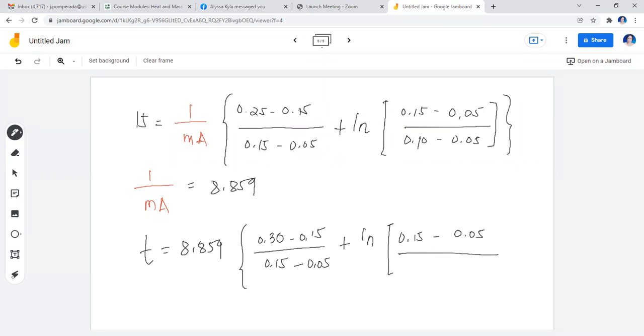In here, instead of 10%, it will end with 8%, and you'll have, again, your equilibrium moisture content here. So for the new set condition wherein we are to determine how long it would take to dry a 30% moisture content material to 8%, the answer is 23.95 kiloseconds.